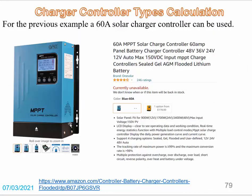So let's see, I made some research from the internet, and I have some charge controller types. So for example, this type we can see from Amazon, it produces about 60 ampere. So we can use this type, 60 ampere, or we can use more than this current, but I prefer to use the correct value, because when the size increases, also the price increases. So the best size is a 60 ampere MPPT solar charger.